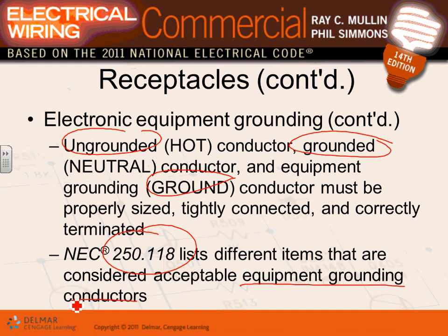So when you have an electrical circuit, here's my circuit, lighting circuit. Here's my bulb coming in here. Here's my 20 amp circuit. Here's my number 12. That's your hot. Then you have to have a neutral to reference it. Here's my neutral, same thing.